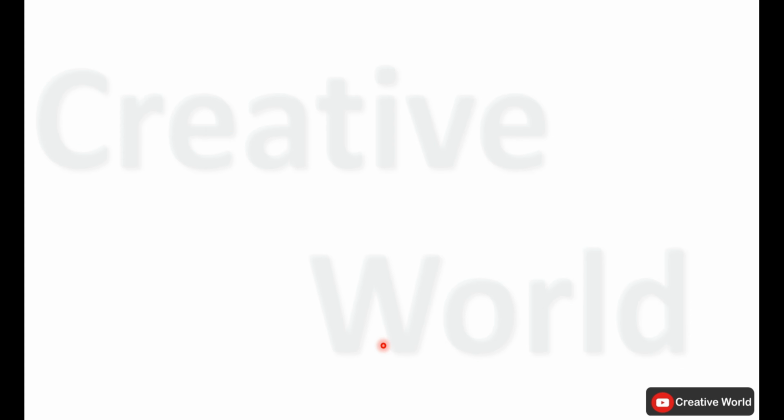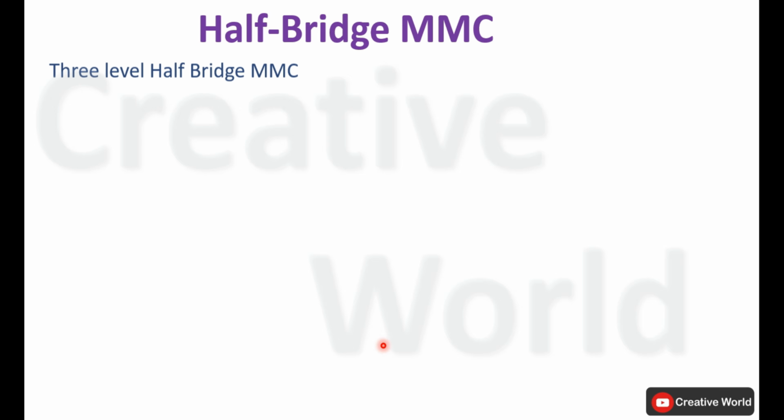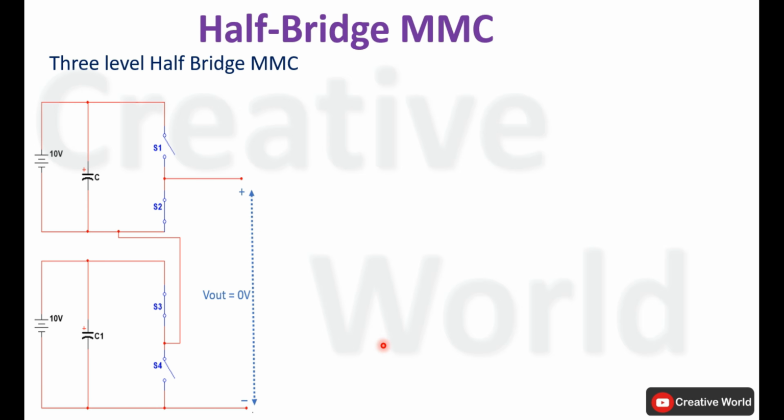Now we will use this half bridge configuration to build a three level voltage. So as we discussed earlier, in order to add the voltage levels we have to add submodules of this configuration in cascaded form. You may see here this is the single module of this half bridge configuration in which two switches are connected in series to a capacitor, and we know that these two switches are reciprocal to each other. If one switch is active, the other one should be deactive, and vice versa.